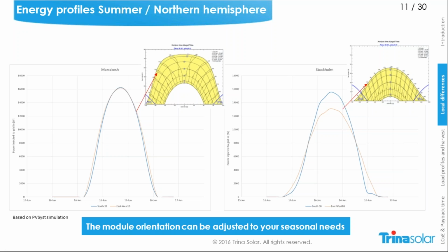During the day, everybody's at work, so the energy consumption or the energy demand of the building will be fairly low. That means even with an east-west system, even knowing, okay, it's maybe not the best solution in terms of highest energy yield, it fits better to my profile because I usually need the energy during evening or morning.